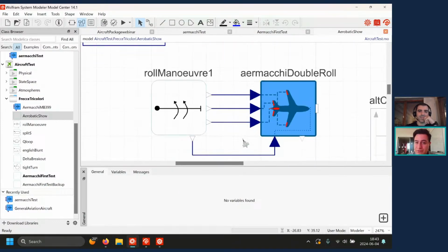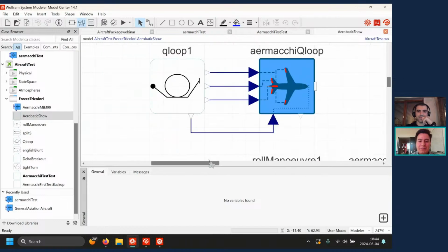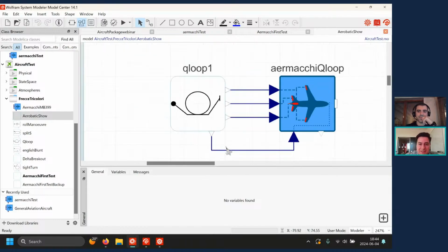The roll maneuver, you have probably seen it in the movies. It's quite straightforward. It's just using your ailerons to roll on top of your x-axis. And this one over here, we'll just be able to see the first half of it since it's quite difficult to model only using pulses, which is the loop. Because the airplane at first is going to gather some energy by going down, and then whoop, it's going to try to go all the way up into its space of least energy, which is going to be all the way here on the top.